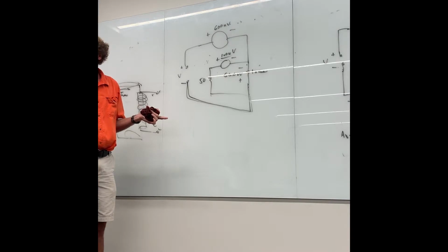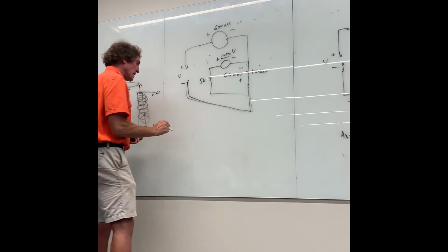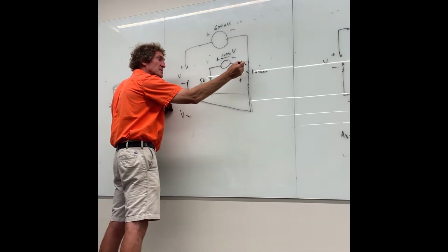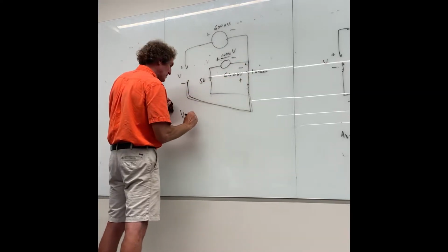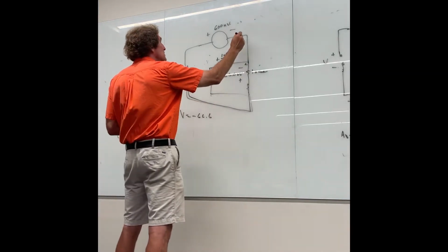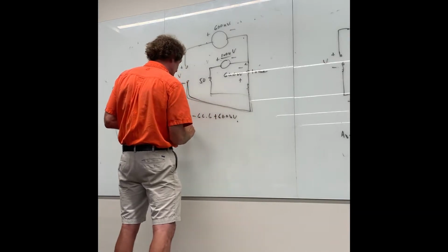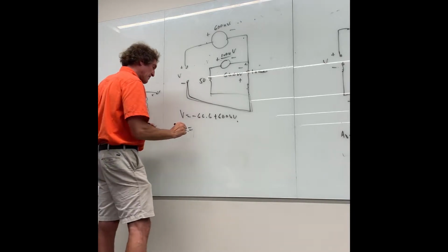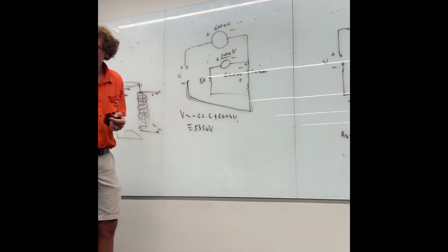Okay, now if that's the case, what's the voltage from here to here? That voltage would be equal to, is this an increase or decrease? Decrease, yeah. It's minus 66.6 microvolts, right? And this would be an increase of plus 600 microvolts. So what does that come out to be? 533 microvolts, approximately. Is that his answer?